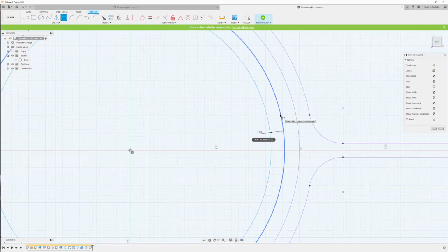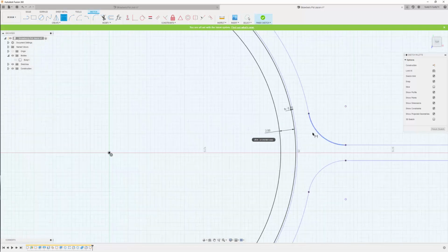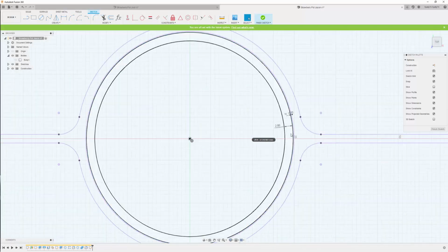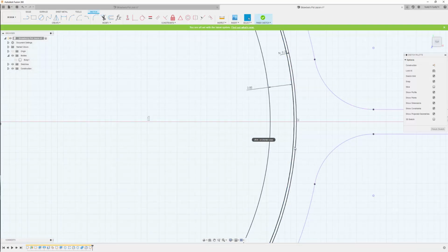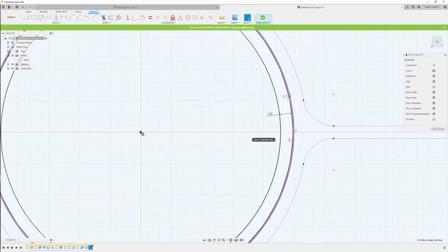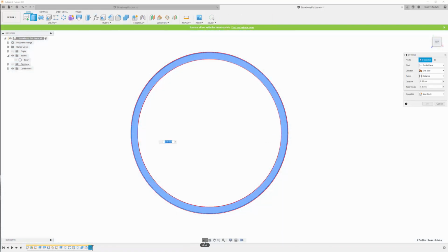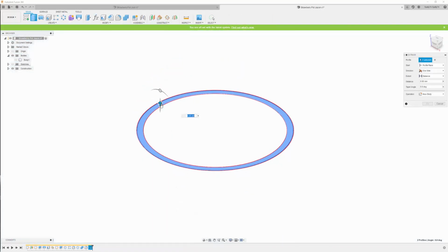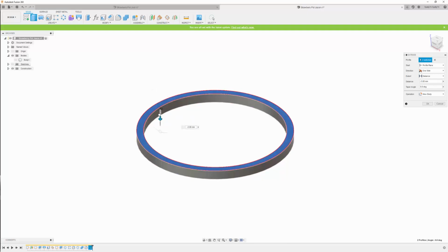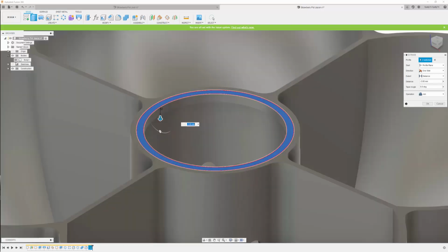And then what I'm going to do is create a sleeve to slide up inside the unit above it. So I know from practice that around 0.2 of a mil, or the value we have, which is clearance, works quite well. So what I can do now is select this object and this one, and we're going to extrude down, and let's go, don't have to go too far, 3mm. We'll turn that body back on, and we're going to do a join command.